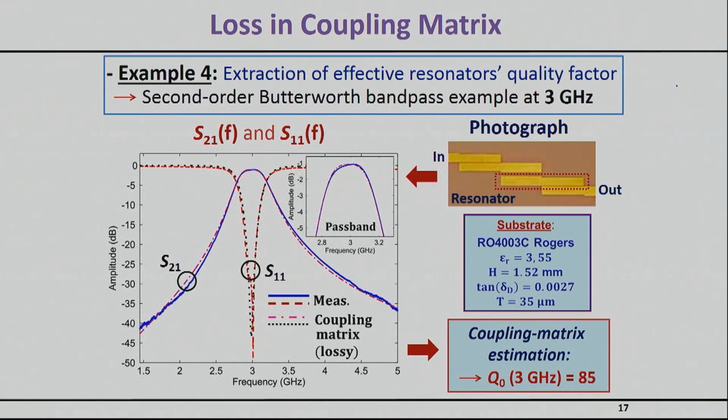So this is an example of a filter shown right here. It's a microstrip filter, and we have not learned yet how to design this type of filter, but you know the concept. The concept is creating resonators. So this is one resonator here, this is the other resonator here, this is the input and this is the output. These are gap coupled resonators, very similar to what we have seen, but the difference is that it's not an edge coupling, it's more of a parallel coupling. So you overlap enough area here to create the correct coupling between the two. The math we have not seen yet, but the concept is known.